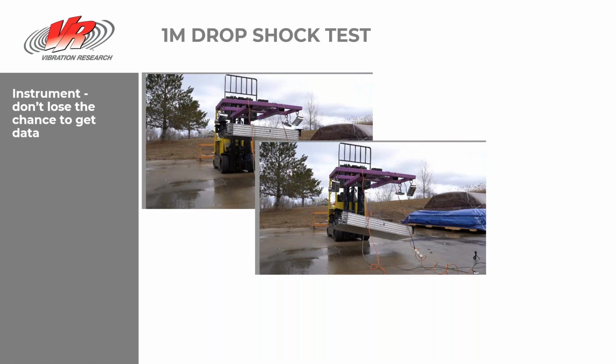So it's very easy to get very different results from what you think is the same test. We always used to run our drop tests on explosives down zip wires and such to ensure that at the point of interface with the ground, it was exactly in the orientation that we wanted. So we had a cradle above it to ensure that it held its orientation until it hit the ground, so we could predetermine exactly what angle we wanted it to hit the ground at.